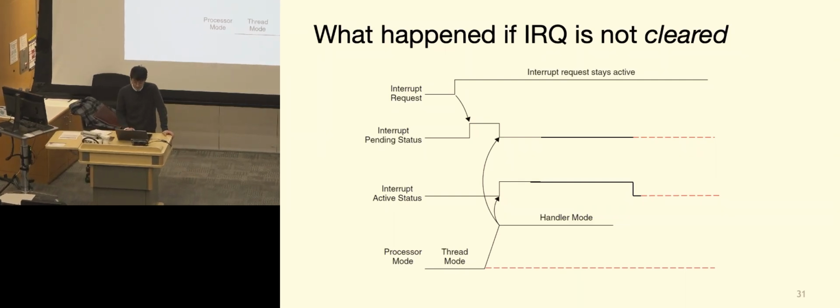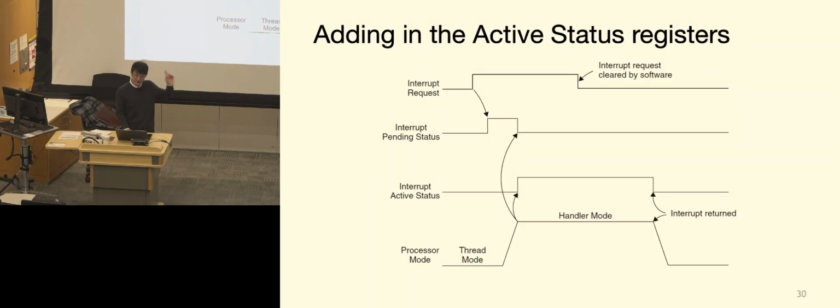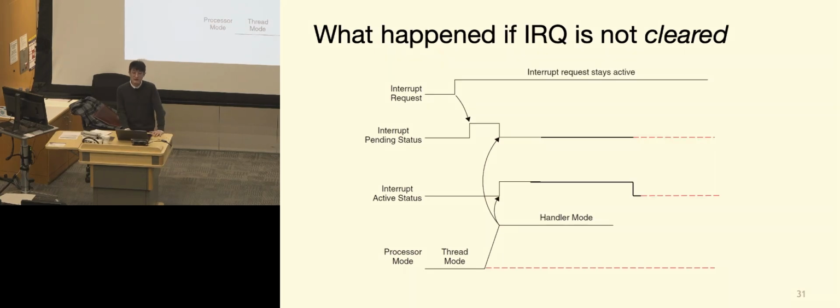And why wouldn't the interrupt request signal here trigger another pending state to go high? Because we think it's triggered on the rising edge of the clock, so it stays high. Anyone else think the same? That is correct.